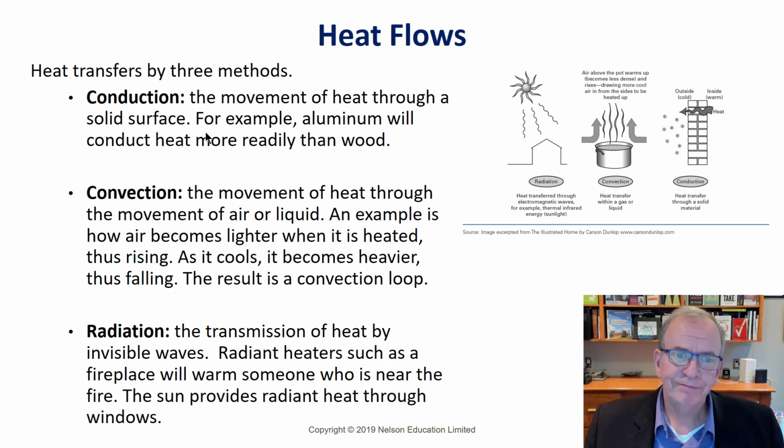And so we've got conduction. Well, heat flows, it just moves through materials, like I was saying earlier, with insulating materials. Concrete is not a good insulator. So heat moves very readily through concrete, and through wood, it's a little bit slower, much slower. And then through insulation, it's much, much slower. So that's why we look at our wall systems. And in the lecture 8C coming up, I talk about what kind of insulation we're putting in, and in 8B, what R value does it have? And then we talk about also the air vapor barriers and what purpose do they serve. So you can think about things in those terms.